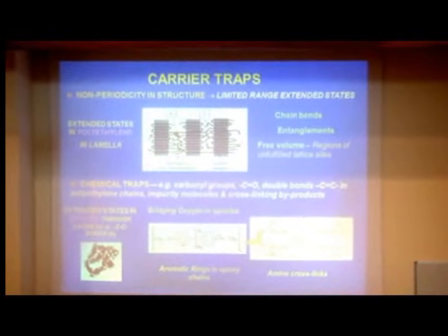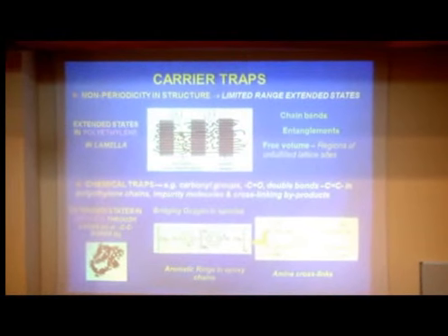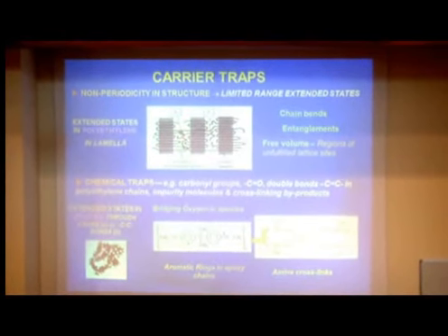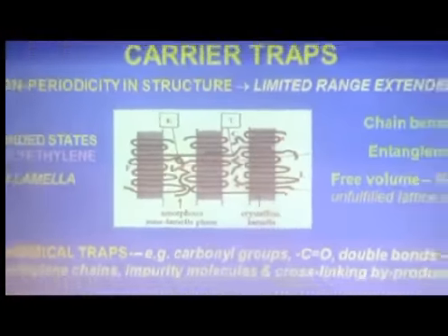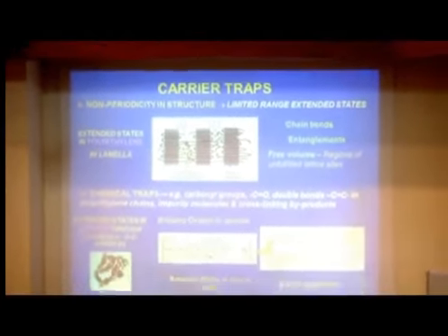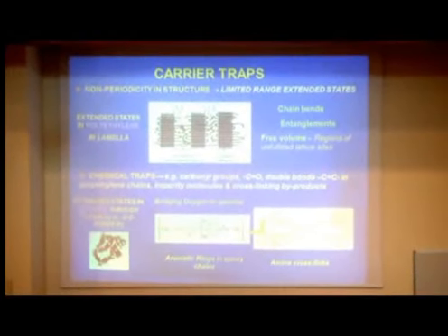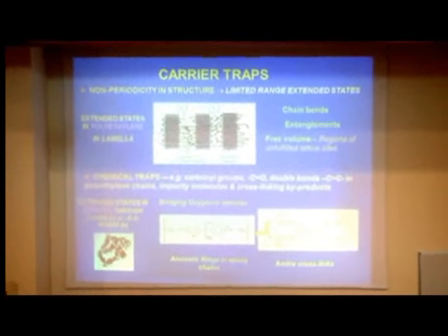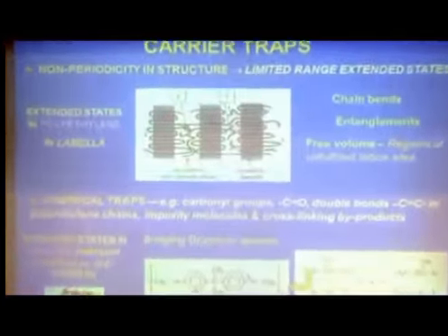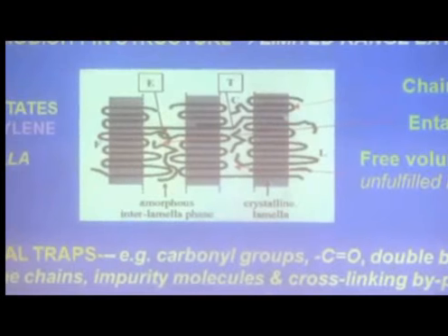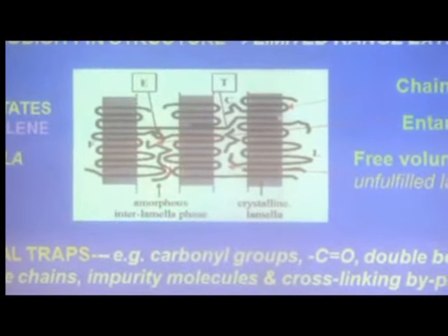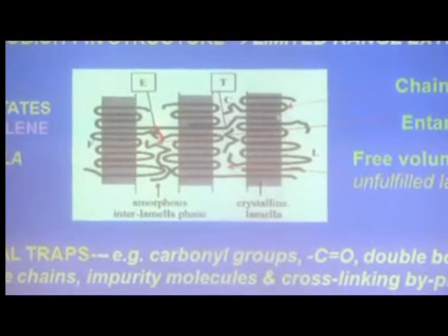So that's saying something of the general picture as to how the carriers move. Let's be a little bit more particular. Here's a semi-crystalline polymer. The crystals are thin plates, much narrower across the plate than they are in width or in length. They're represented here by these grey bars, and what you find is the polymer chain is very long. It moves into the crystal and curls around, but it can move between different crystal plates. It can move into the intermediate region where other chains are located.